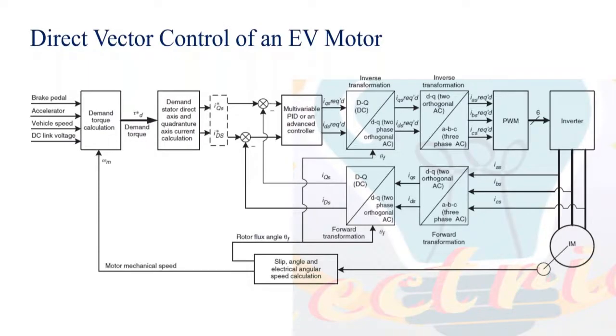So using the four mathematical transformations, the controller determines what is the exact current that the motor has to be provided. After the transformation, the motor gives the IA, IB, IC values, based on which you determine the switch signals, which switch should open. Based on that, once again the feedback is received, once again you calculate, once again run the motor, once again feedback. This cycle keeps on running continuously when you are operating the motor.